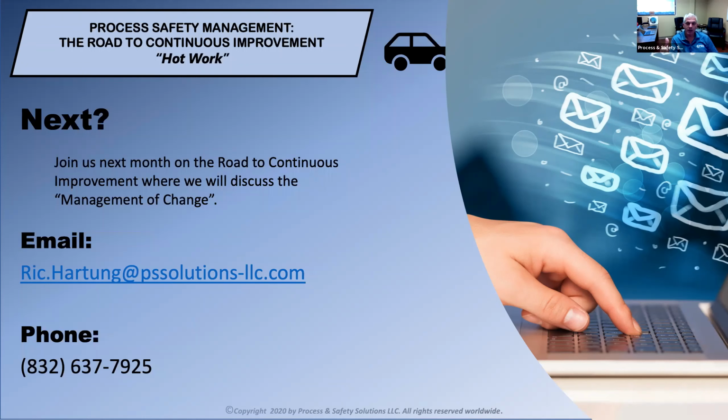Also, the monitoring of ambient air conditions, for example, shouldn't go a total of 8 hours before you do that. You should be monitoring that air at a minimum of every 4 hours to make sure that nothing has changed. And certainly I wouldn't allow a hot work permit to transcend multiple days or even multiple shifts for that matter, because those people and those personnel change as well. So we want to make sure that a new hot work permit is issued at least every shift change.